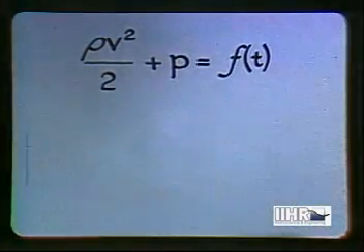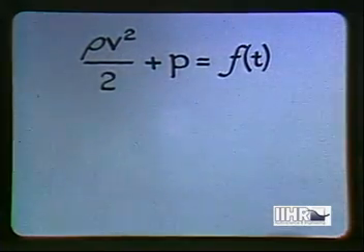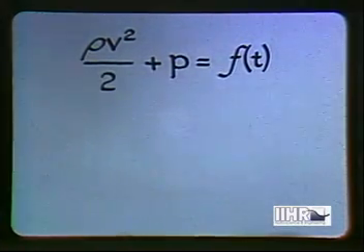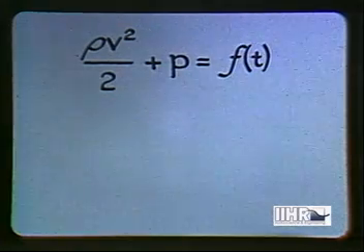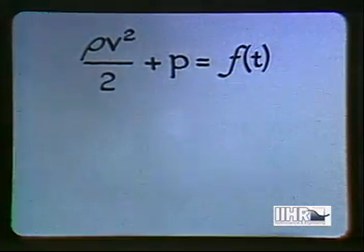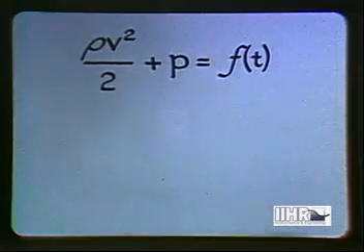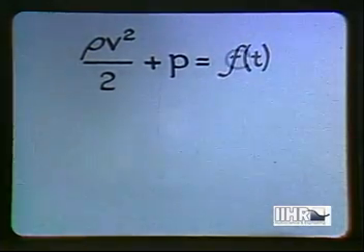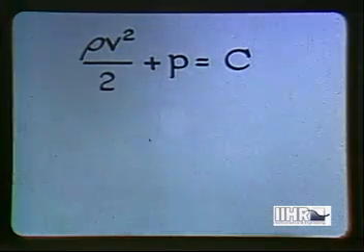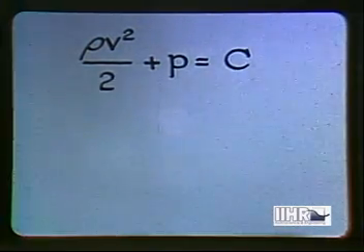For the present, let us note that for steady, irrotational flow, the equations of acceleration can be integrated to yield a very convenient and significant pressure-velocity relationship. This states that at any instant, the sum of what is sometimes called dynamic pressure and static pressure must be independent of location, but not of time. This sum will be independent of time as well, if the overall pressure load does not vary.